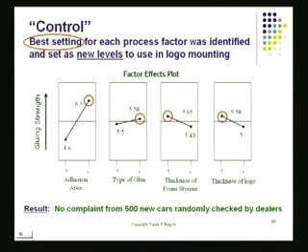If you run into a situation when there are many factors involved in a process, and it turns out that you'll have a very large number of trials to be done, for example, in this case, 2 to the power 7 trials, think of either consulting with a master black belt or use your own training, pull out a textbook on statistics and start paging through those pages on orthogonal array designs.